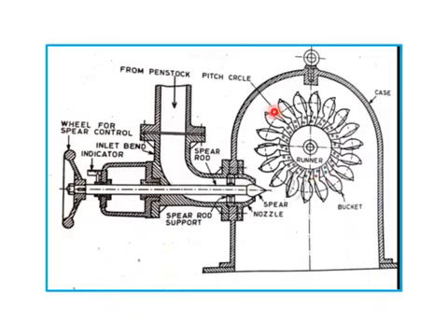Now this is the case I was discussing for the tangential flow turbine. These are the series of buckets that are mounted on the runner. When you join the centers of the buckets, we get a circle that is known as a pitch circle. Now the water is striking in this direction, straight, and then it hits the tangent to this circle. That's why it is known as a tangential flow turbine. Example is the Pelton wheel.